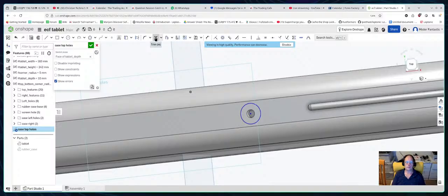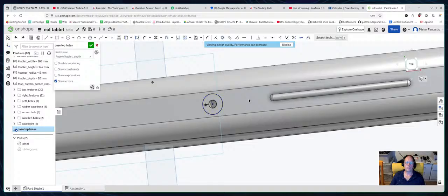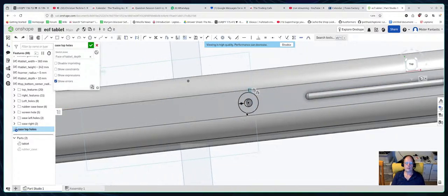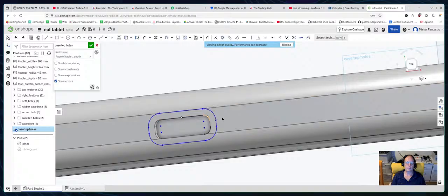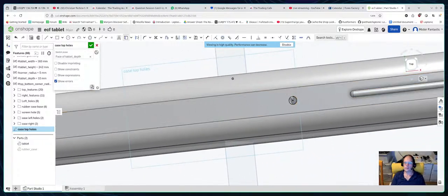That's done. Great. And then now you know what, here it's black, that means it's got a reference or something that's outside. I've got to undo everything. I've got to undelete that stuff that I deleted until that rectangle turns black. There we go. And then I've got to use this and offset that. One. Done.